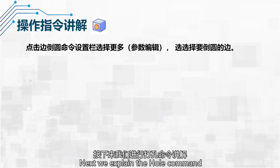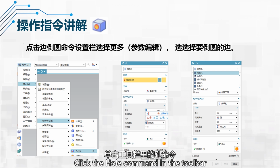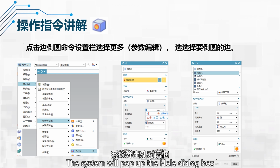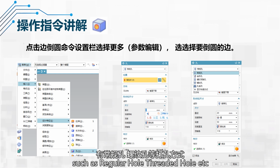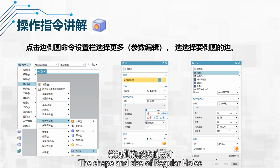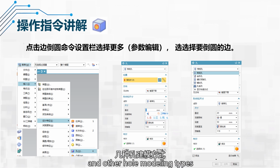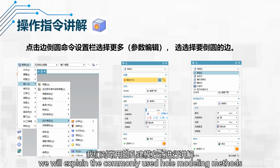Next, we explain the hole command. Click the hole command in the toolbar or in the drop-down menu. Click Insert, Design Feature, Hole. The system will pop up the hole dialog box, such as regular hole, threaded hole, etc. The shapes and sizes of regular holes include simple hole, countersunk hole, counterbore hole, and other hole modeling types. Next, we will explain the commonly used hole modeling methods.